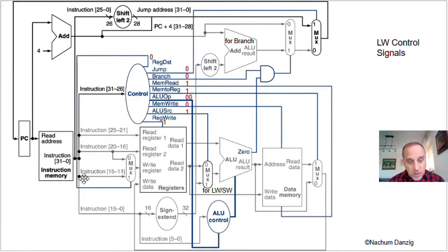But those bits start going here. And if you notice, 15 to 11 go here, but also 15 to 0. That means the whole immediate value goes down on these lines. So we have some splicing going on. In other words, some of the lines are coming out and turning here, and there's a little black dot here, which means not only do those lines go this way, they continue also this way. You can imagine an electrician cut the wire and spliced in a new wire, so it forks. So the electricity goes both ways at the same time. That's what's going on over here.